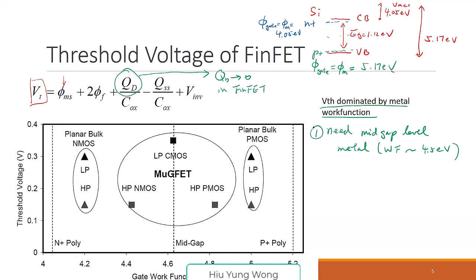What's so special, right? So yeah, nowadays we keep saying that we use metal gates. The benefit is it has smaller resistance, right? You have less delay. Great. But actually, we were kind of forced to do that at the beginning, because we need to find some work function that is between the N+ and P+ poly to have the correct VTH.